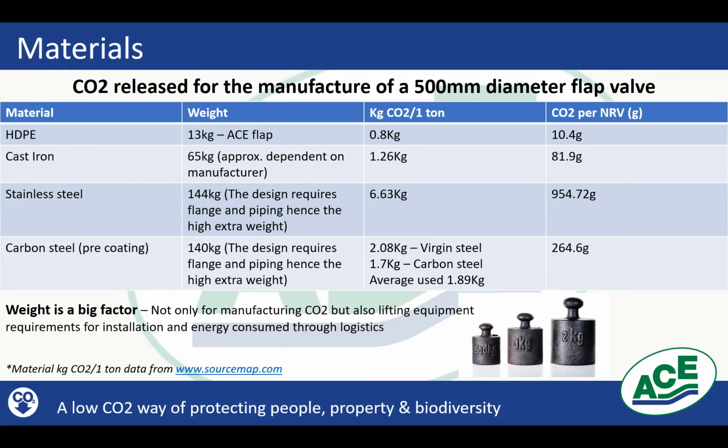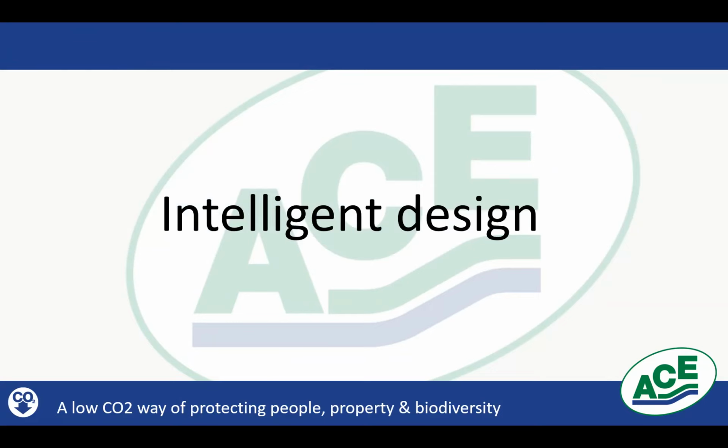So you can see enormous differences, and that's because the weight is so critical when looking at producing low CO2 outputs. Now remember, it's not just about the weight of the valve. The HDPE is lighter, so it saves CO2 on transport and the logistics getting it to site. Also, as I mentioned earlier, it could massively reduce the lifting equipment. I mean, when you're looking at this, 13 kilos, that's one man that can install that. 65 kilos, you're starting to have to consider possibly a very small excavator or a high-ab or something, because it's beyond the safe lift of two men.